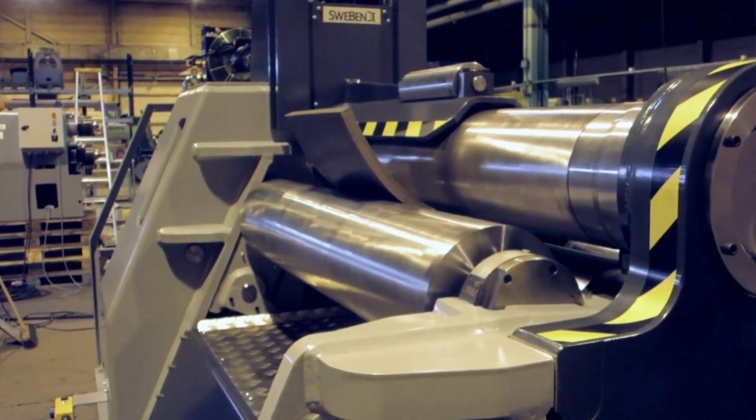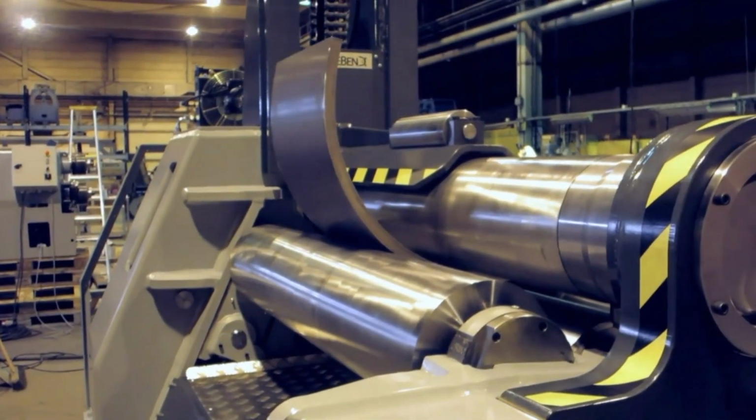That is, we start with the flat pattern, and without distortion, we change it into the desired shape, as cylinders, cones, transitions, Ys, branches, and so on. This is by folding or rolling the flat sheet metal pattern. In the case of spheres, the rolling is not linear in one direction like with a cylinder or cone, but actually it is radial. In the case of sheetmetalpatternonline.com, the shaping is considered without thinning nor stretching of the metal sheet. This is the case of dishing.